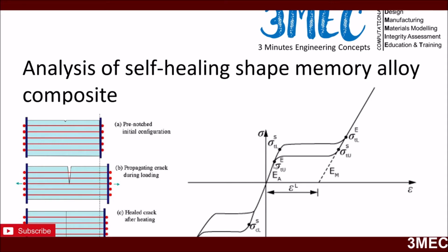And if you know the theory of shape memory alloys, they can have elastic deformation in the austenitic phase, and then they start to transform into martensitic phase, and then they completely become martensite, and then everything is governed by that. Now if you unload the sample again, which is already transformed, then it retransforms back to the austenitic phase. So this is martensitic phase, this area, and this is in between, and this is complete transformation back to austenitic phase, and the same happens in the compression side as well.